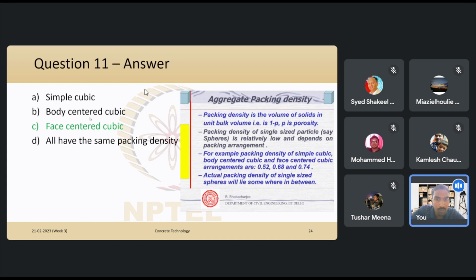So in this, if you look at it, there is a single particle within the center, right? So its volume is completely within the cube, and again there is going to be 1/4 of the volume from the corner particles, right? So again there are 8 corners, so therefore effectively it is like having 2 spherical particles inside the cube, right? So that is the body centered cubic arrangement.